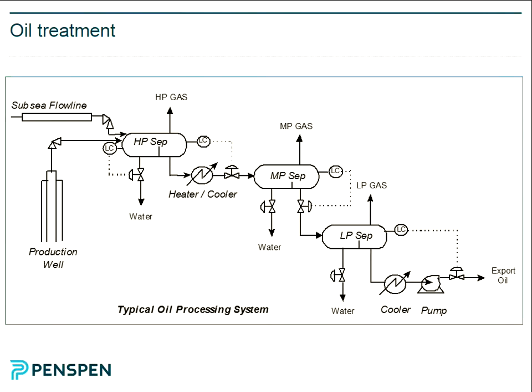And this is kind of the building block of oil processing, the separator. This is the conventional gravity-based one. So at the inlet, you've got a momentum absorber. This is multi-phase flow, so if you're getting slugs of liquid arising, it's taking out the momentum. So you're not creating waves here. You want it to be relatively flat.